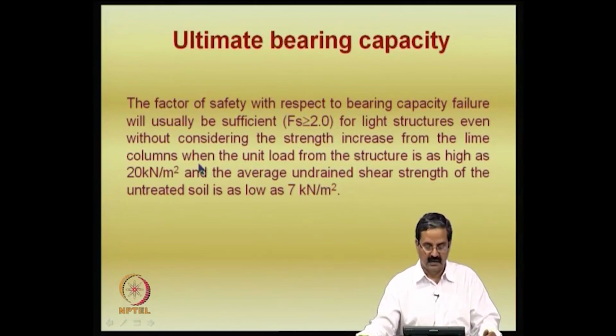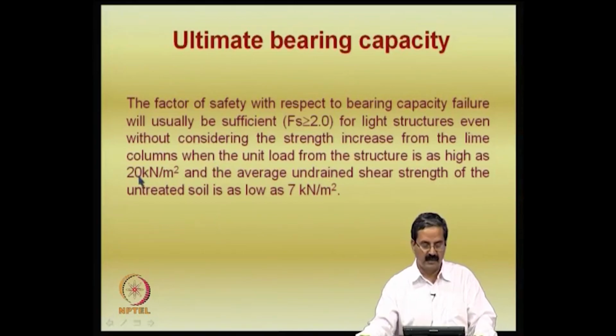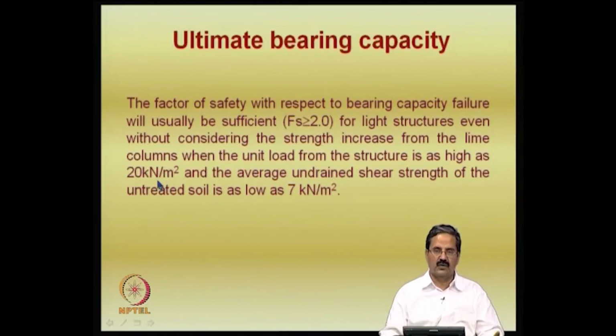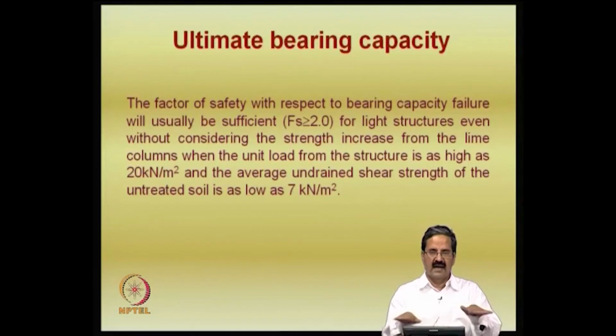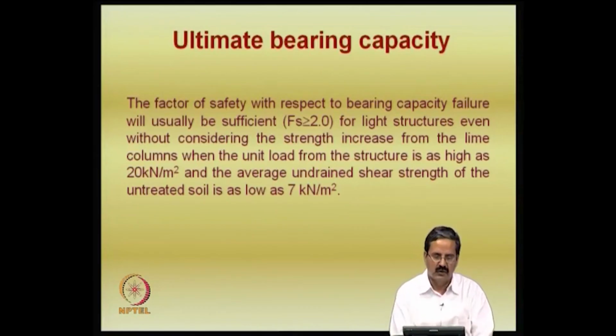The same assumption one can use when the loads could be about 20 kPa actually. Even the IRC code says that you have to take the load on the highway as 1.2 times the unit weight of the soil times the height, say 1.2 into h, where h is, for example, 1 meter or 2 meters, and the unit weight we know. So, you just multiply, and it comes to about 22 kPa. It is also similar, 20 kPa is what we assume for bridges or pavements.